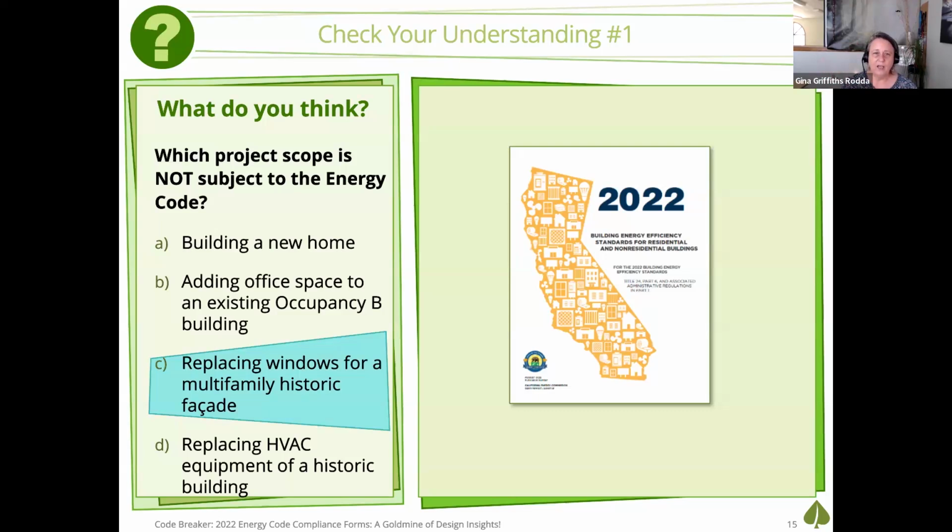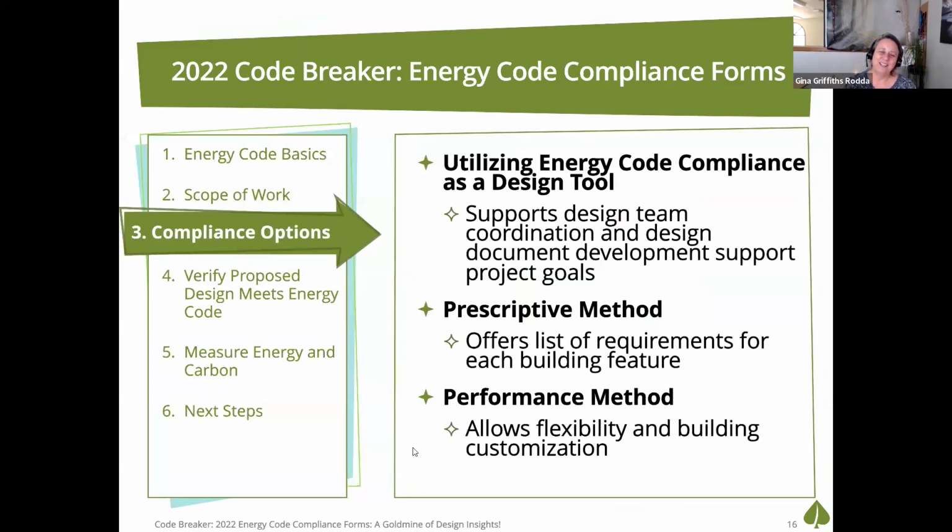envelope. And because it's a qualified historic building or just a facade, I have in San Francisco, I might just have a facade that's qualified, but the entire building is not. So sometimes we want to look at the specific facade of the building. Is it qualified historic? Anything you do to the envelope of that qualified historic feature would be exempt. That would never be mechanical equipment. You don't get to keep that old oil furnace because it's historic if it has to be replaced.